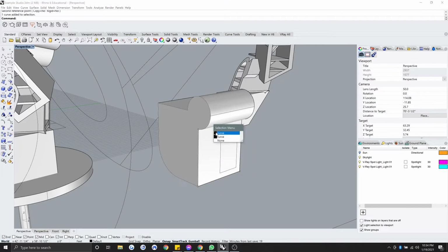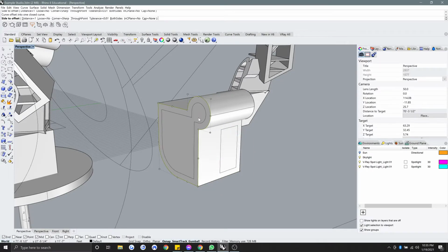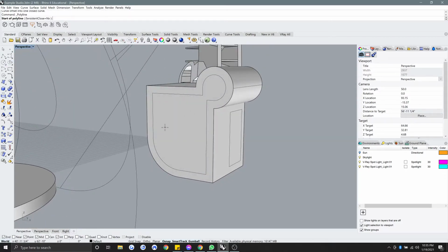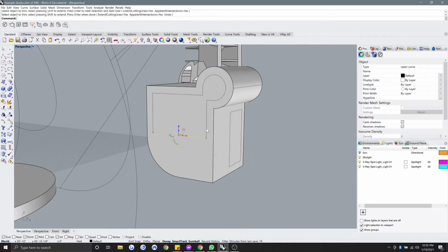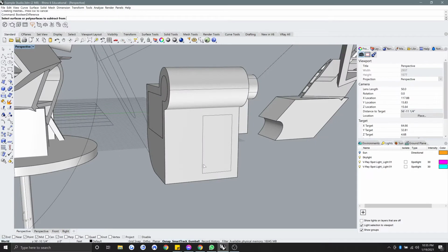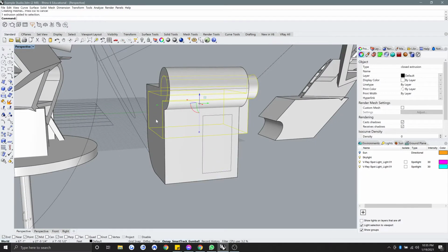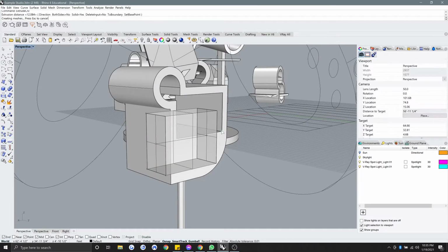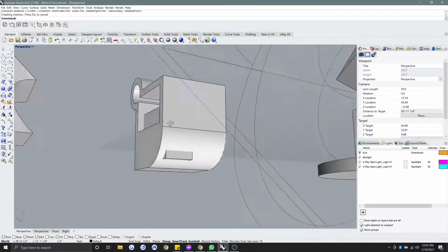And then I'll take this one, offset it again to my base distance, and then maybe I'll cut it off at this halfway, which will mean that I'm going to click on this line, trim, click on the bottom part here, and join that. So now when I extrude this through, I'll Boolean difference this with that, delete this part, and I'll do the same thing here. Extrude this, but I'll only go to this wall.